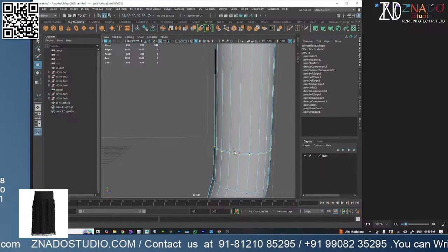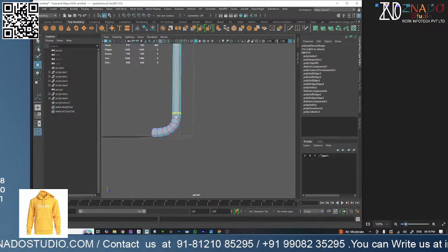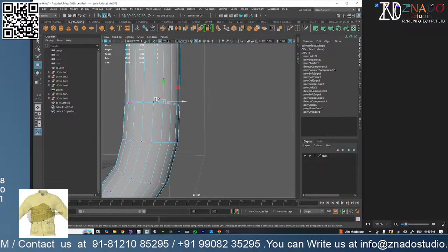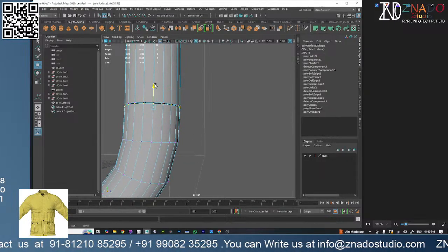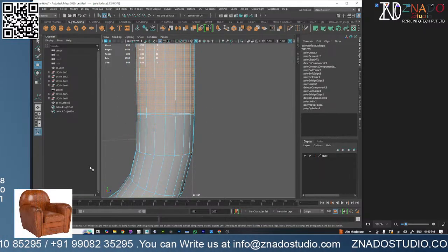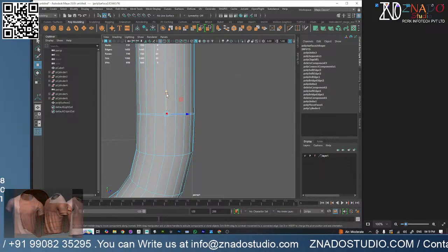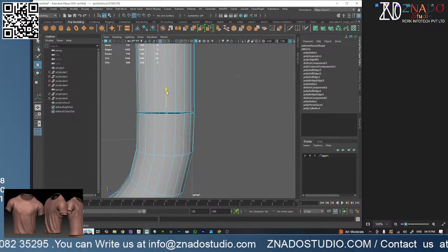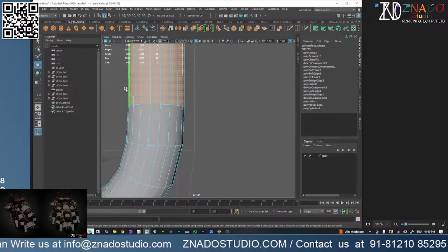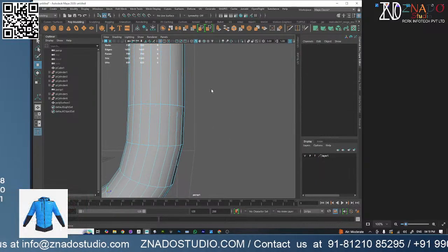The vertices are there but not merged together, it's almost there. What we'll do is select these edges, okay, not this one, this is the edge. So we select the faces, we don't want this, we'll just pull it up or use vertex snap. Done. Select the faces from here, both sides, and delete.